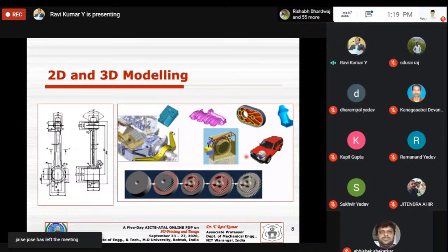As far as 3D printing is concerned, solid model is preferably the ideal choice, but surface models can also be accepted by the 3D printer. That should be in STL file format, free from open surfaces or flipped normals. But preferably a solid model is the ideal choice, as we know it is a more complete representation than a surface or a wireframe model.